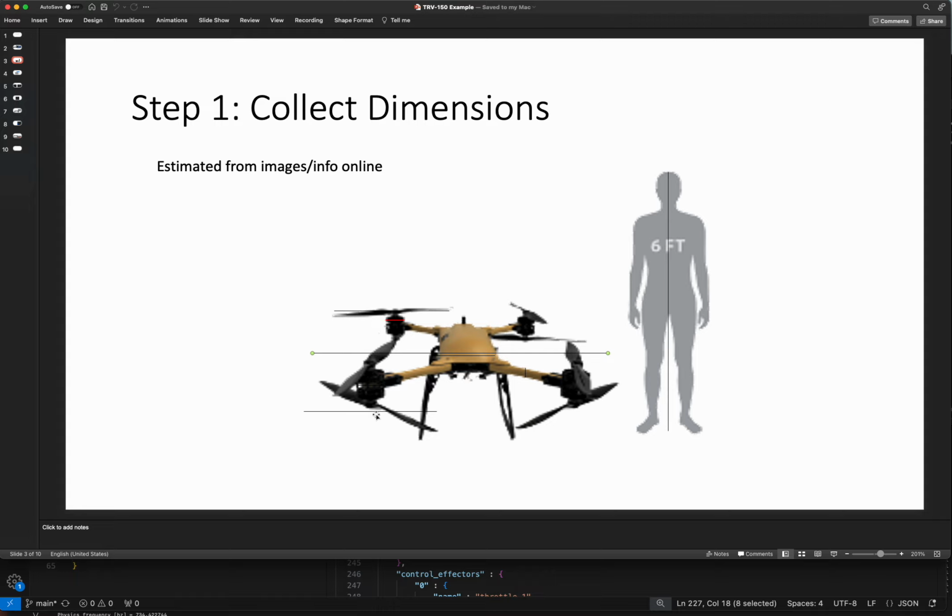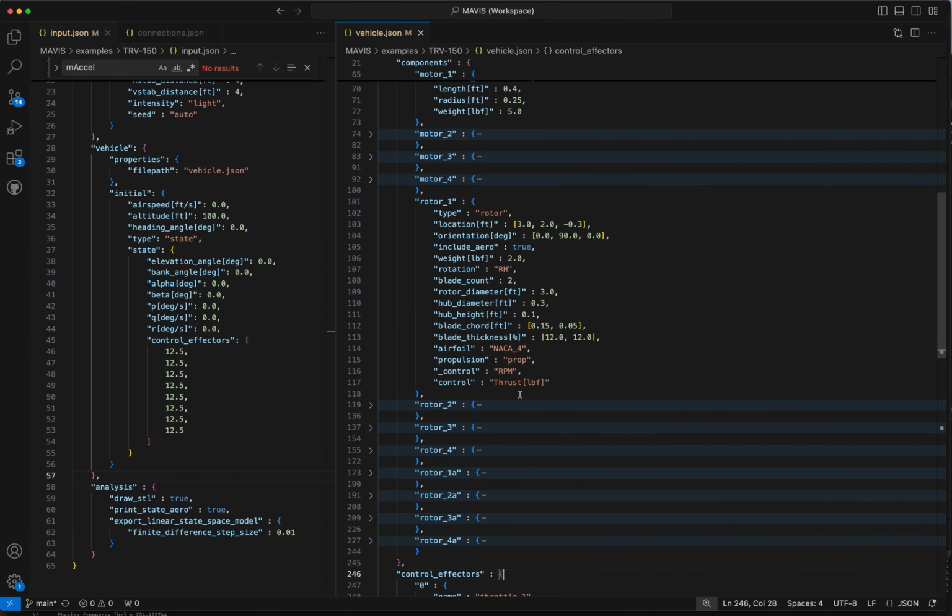The lower rotor looks like a left-handed rotor to me, and I think this is pretty universal, that you basically make the two opposite each other here both right-handed. These two would be both left-handed for the upper level, and then the lower level is just the opposite for each of those. So the right-handed is paired with the left-handed below that, and that just helps with some of the torque and aerodynamics caused by these rotors to balance it out.